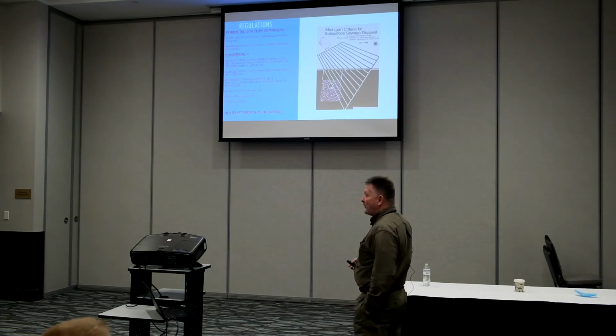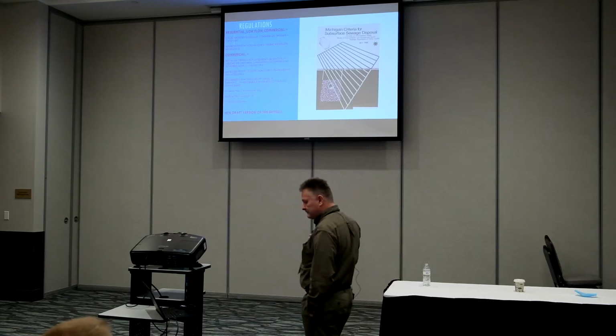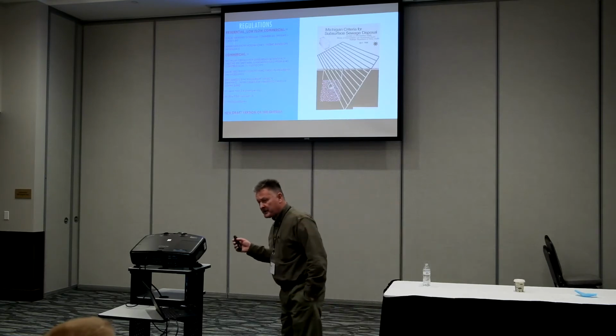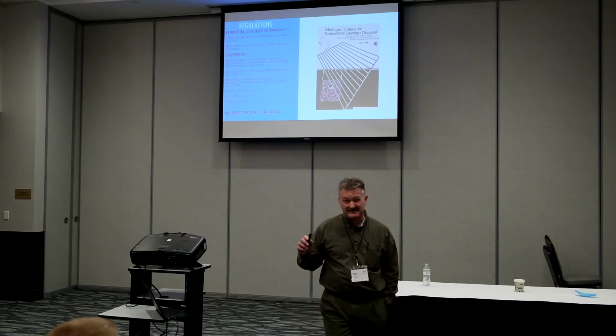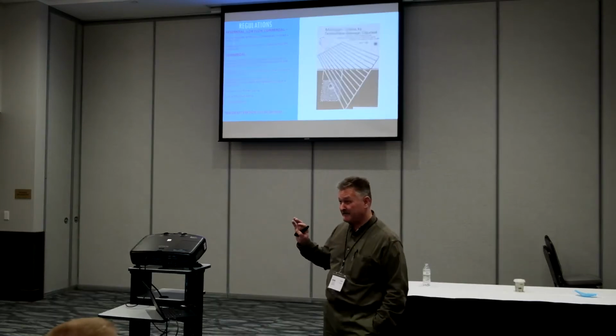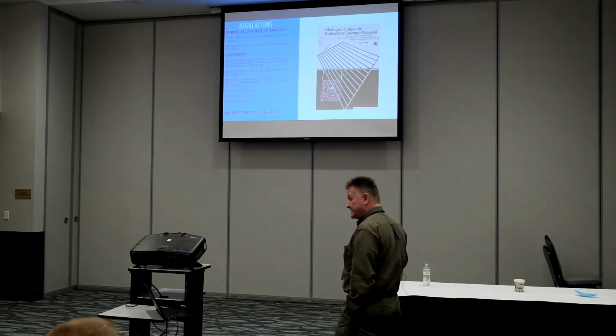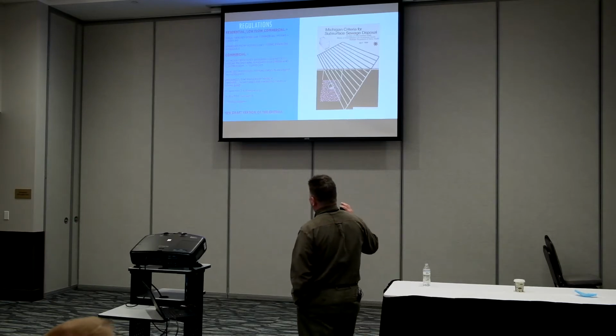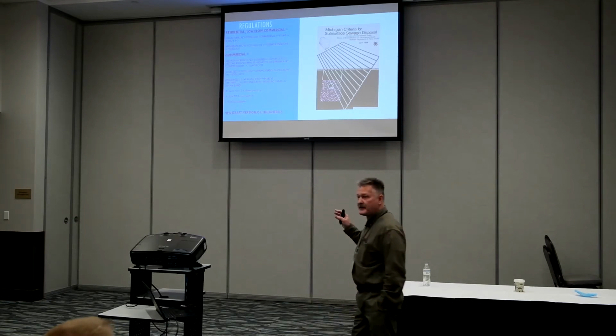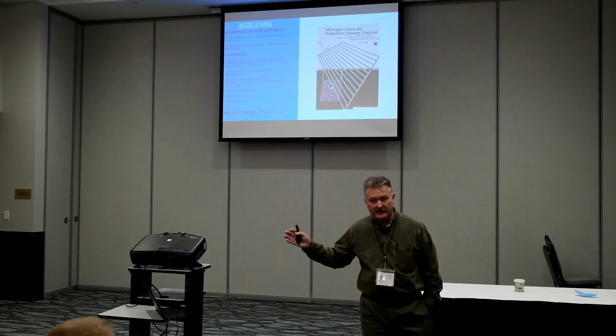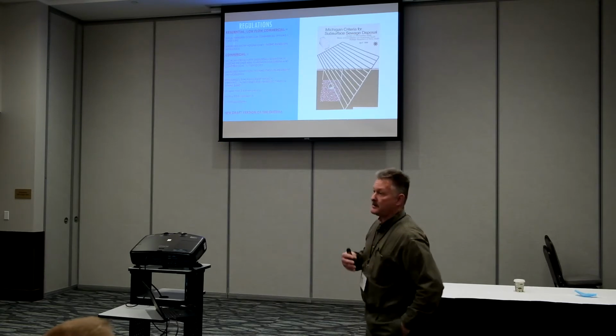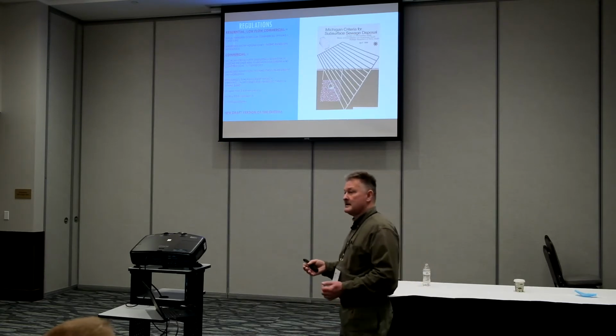Now when we talk about commercial applications, oftentimes we still apply that prescriptive mentality onto high strength situations. For instance, with our regulations, if that commercial flow is less than 1,000 gallons per day, you can apply your sanitary code.